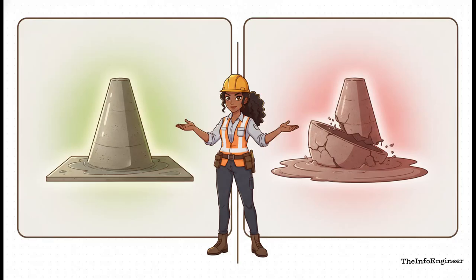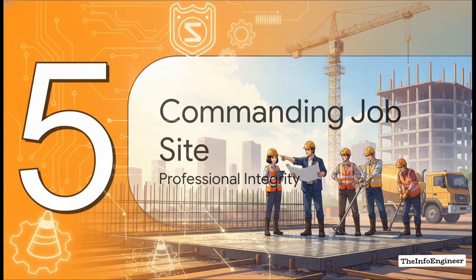So, to sum up your diagnostics here, a true slump provides a meaningful result and allows you to proceed with measuring and reporting. But if you get consecutive shear or collapse slumps, those are invalid results. It simply means the concrete lacks the fundamental plasticity required for the ASTM C143 method entirely, and honestly, the batch is just fundamentally flawed.